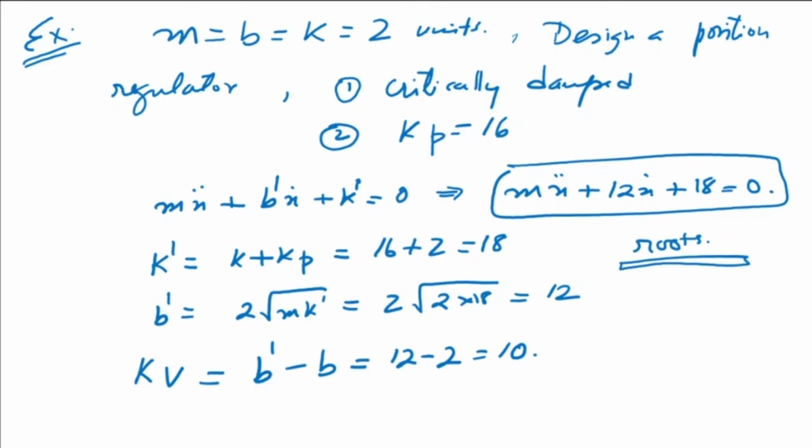Now we find the response of the system, that is, I take it to some point and I leave it. Suppose it oscillates like this and comes to rest, and we are happy with that. Then we say that this is fine. But suppose it did not do that, and instead it went very slowly there. Then we are not happy with this. Then what you do is increase the Kp gain. What the proportional gain does is it increases how fast it is going to come back.